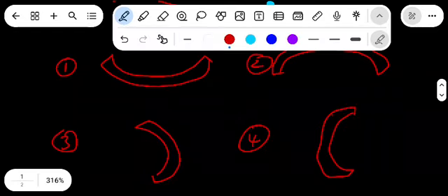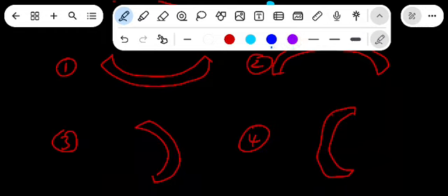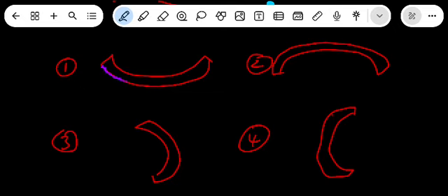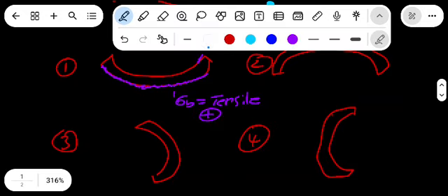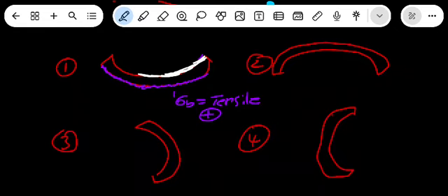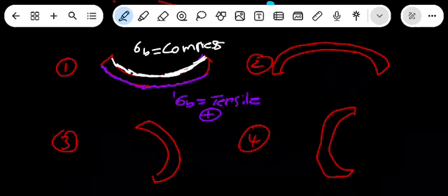So when we identify the bending stress in this portion, the one I'm showing, on that side, our bending stress here will be tensile. That means you'll take it as positive. But here on the top part, where the bar is bending, the bending stress will be compressive.